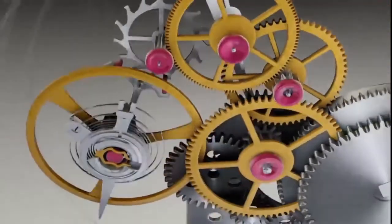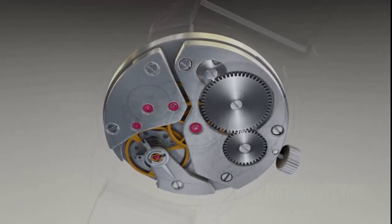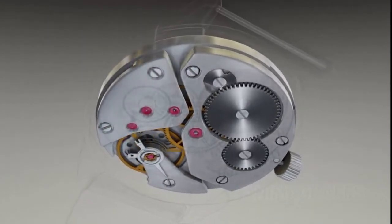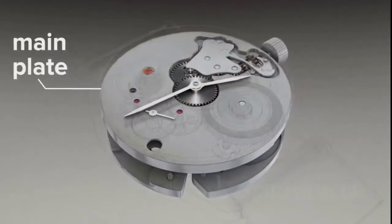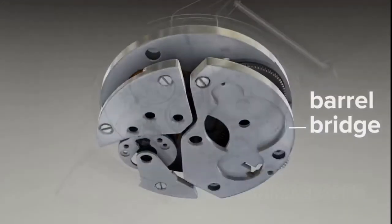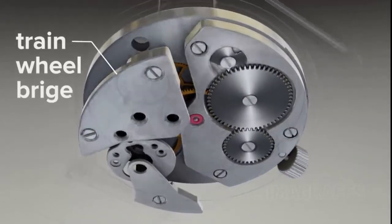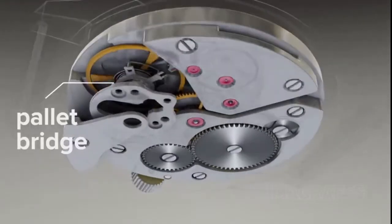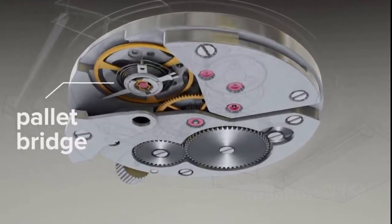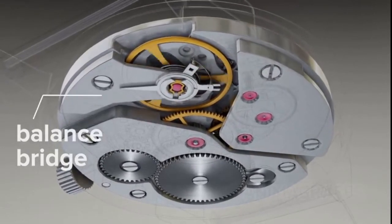Supporting structure. Various specially shaped metal plates support watch internals. The main plate serves as the base. The barrel bridge holds the mainspring barrel and associated parts. The train wheel bridge supports the wheel train. The pallet bridge holds the pallet fork, and the balance bridge supports the balance wheel and regulator assembly.